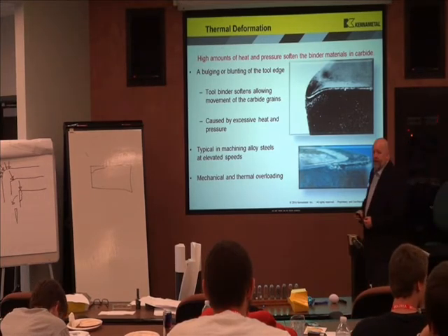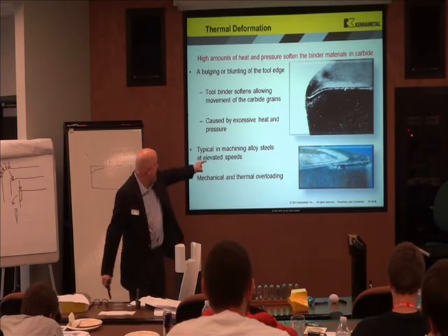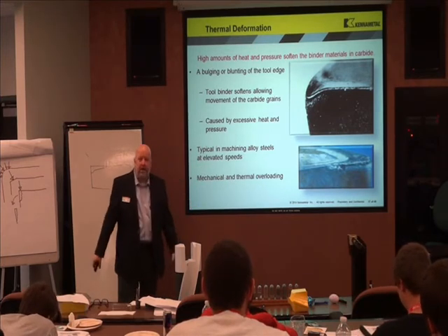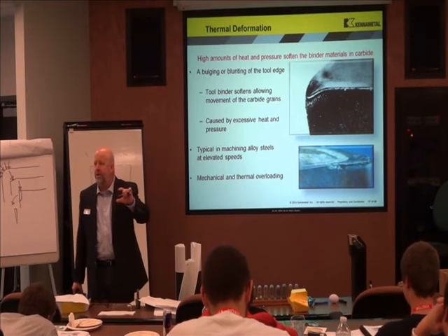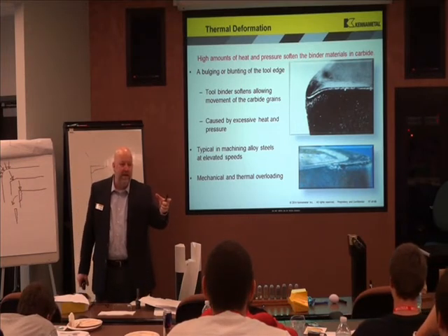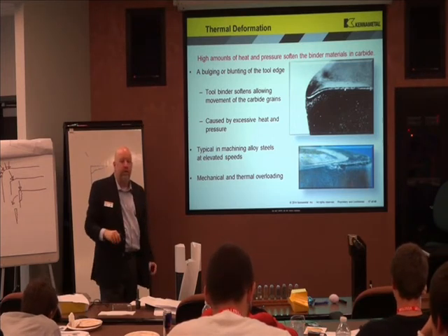This is my favorite. This is thermal deformation. What two things does it take to make a chip? Heat and pressure. What do you think happened here? Way too much heat and pressure. Instead of plastically deforming and shearing away my chip, I'm plastically deforming the tool. Usually you will not see this. Usually the old corner of the tool's gone.